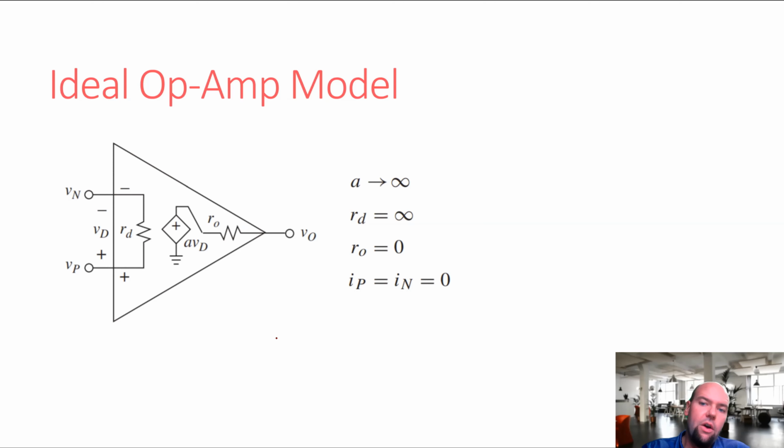So not always. Again, sometimes to be faster, they'll use a BJT or something. Older op-amp designs use BJTs. You're not going to get no current flow into those. That's not the same as an oxide gate. So some of those will have an input resistance that can be anywhere from 10, usually it's 100,000 ohms or more, but it varies. But there are op-amps, many op-amps, where this input resistance being infinite is a very good assumption.